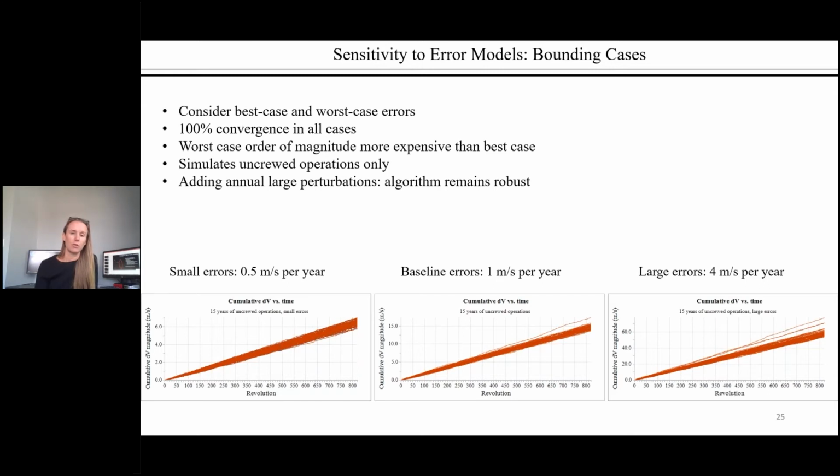simple situation in order to design the algorithm, and then we also, of course, run 15-year simulations with FreeFlyer of orbit maintenance costs and attitude control costs, assuming all the dockings and the perturbations that you expect from crewed missions to Gateway as well. I also tried to break this, because we had a pretty cool algorithm design to get back to the NRHO if we accidentally left.